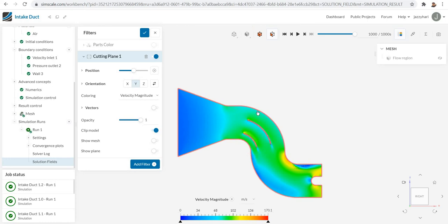Now we can see in all this area, the green color is almost distributed everywhere, and only in very small areas the color is varying. So the velocity is uniformly distributed, since the cross section is not varying, and the losses will be very less. The flow separation is not as big as we saw in the rudimentary design. The modified design is quite impressive.